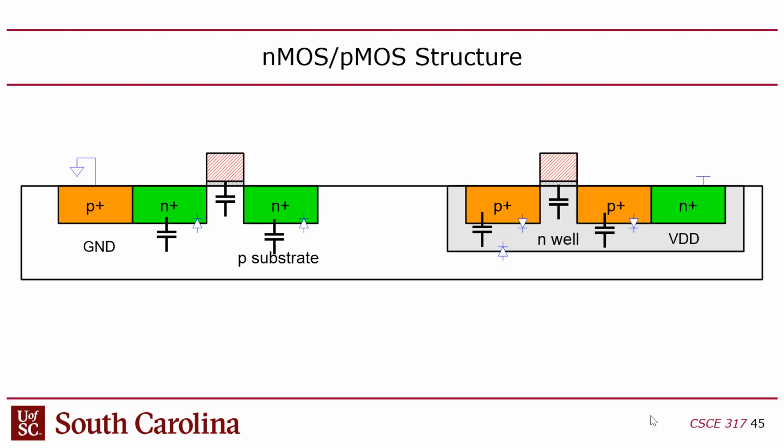This turns out to be really significant because these guys have capacitors. And remember I mentioned that with a logic gate, it's the source and drain that's actually driving the output of the logic gate. The gate is the input of the logic gate. So the capacitance you get from gate to gate starts at the source and drain, and then you connect to the gate, which is the input of the next gate downstream, and that has a capacitor too. So you have to add all that capacitance up.